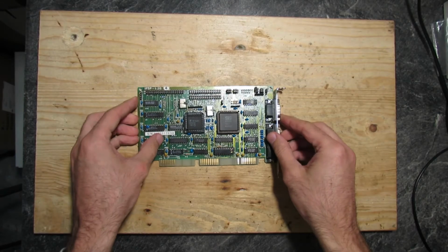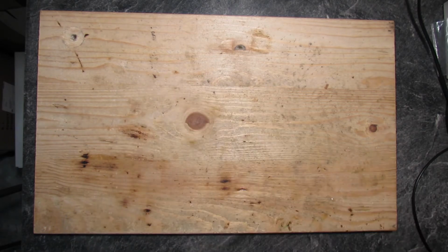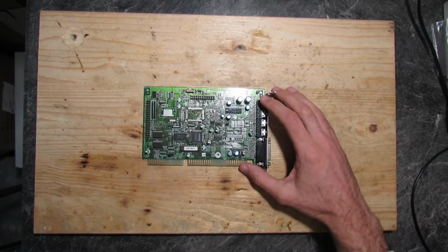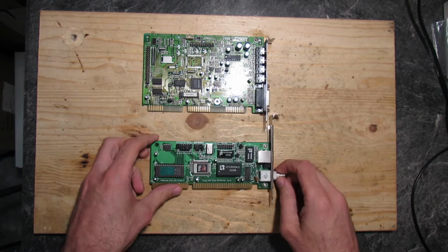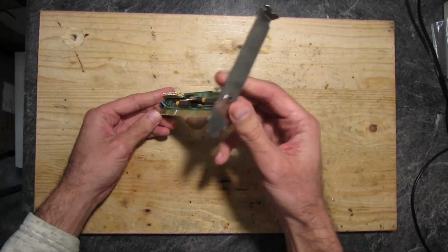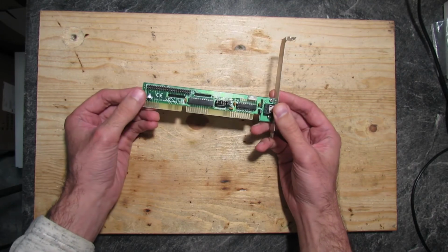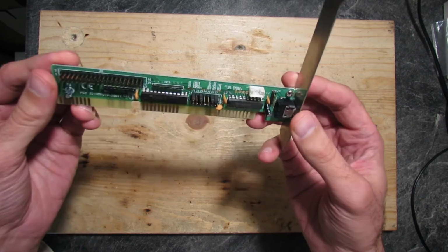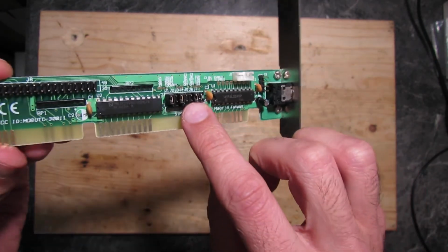This trick can be helpful if you don't have an IDE controller at hand, or if all of your ISA slots are full, but you want to have a sound card. In such a case, you could swap your normal IDE controller for a sound card and have network and sound capabilities on a mainboard with only two ISA slots. As a bonus, you can also use dedicated IDE CD-ROM controller cards like this one, as long as they also have jumpers and don't need any special driver.